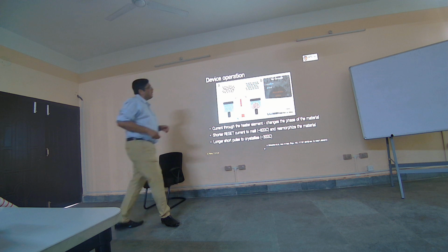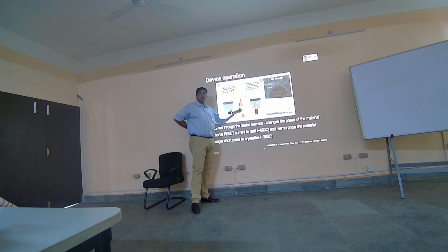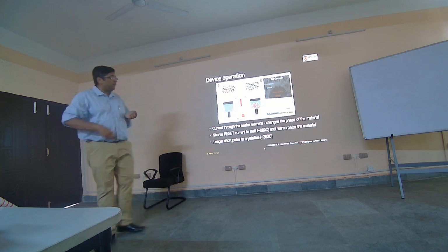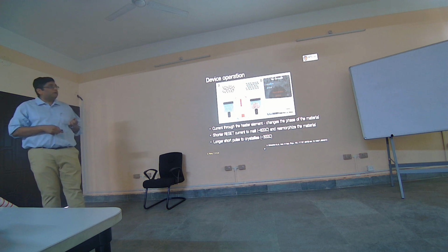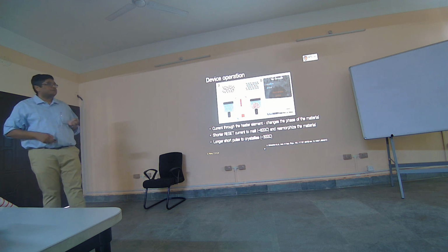What happens is that if you apply a very high current for a short time, the temperature is going to rise very quickly and it's going to cool down instantly. And so it ends up amorphizing. However, if you apply a current for a longer time, it melts, and since you're giving it a slow time to cool down, it is going to get into the crystalline state. So by applying the right pulse, you can convert the material into either a low resistance or a high resistance phase.